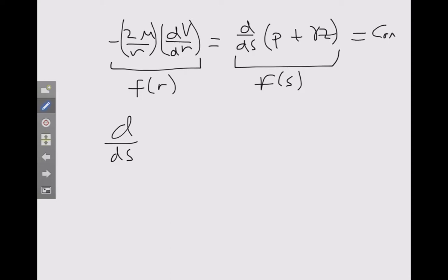We'll just call it a constant, and therefore we can rewrite this as a constant. In fact, we can manipulate it as the book does and rewrite it like this. Since the piezometric pressure gradient is constant along the pipe, we can rewrite it like this, where this is now the piezometric head.